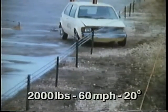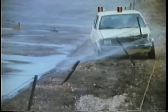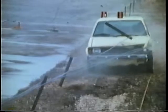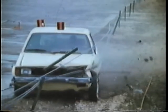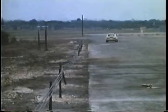In this test of the South Dakota system, the cables wrap around the front corner of the small car when it hits the barrier. The cable slips off the post ahead of the collision, and the posts either snap off or bend over as they're struck by the car. The cables redirect the car parallel to the barrier. It comes to a controlled stop after braking.